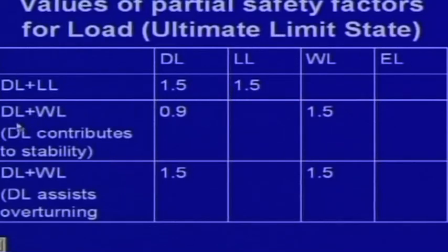If you consider dead load and wind load, then dead load contributes to stability when you are considering that aspect. So, we are assuming a little less from the stability point of view, because you are considering from the safety point of view, the other side. I mean to say, if you take less dead load, then from the stability point of view, the wind is more, so it may become unstable. That part you are considering, that is why you are reducing that load, and wind load you can multiply with, say, 1.5.